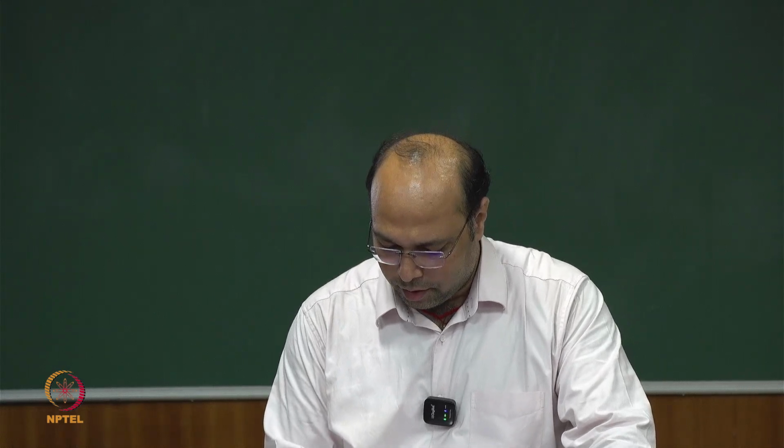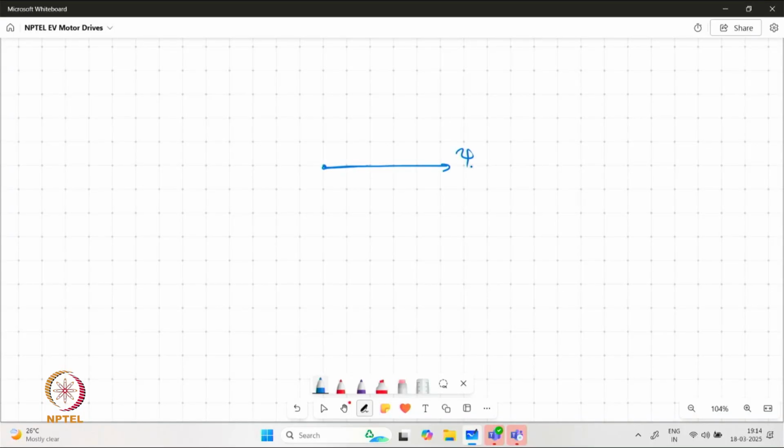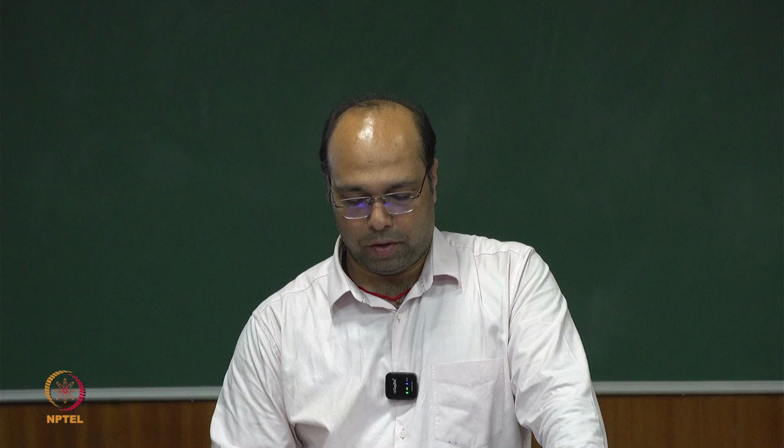So we have indicated that psi m and IR are interacting to generate the torque in the machine. The fundamental torque in the machine is generated by this interaction. So we can take a constant and we can take the magnitude of the cross product of psi m cross IR, and we can as well take the vectorial representation of these quantities. For convenience, we can define the quantities in the stator frame of reference, so for having the clarity of where we are going to express these units.